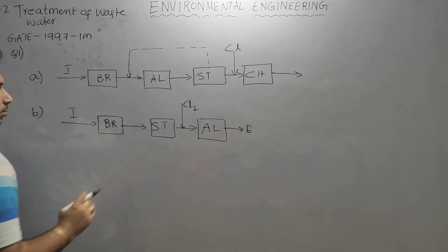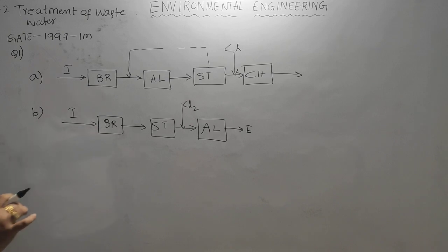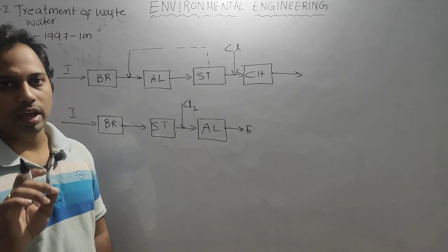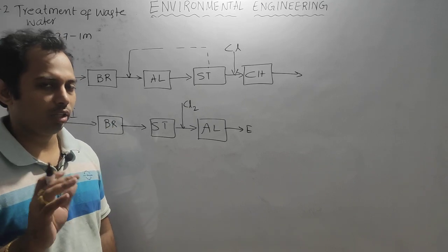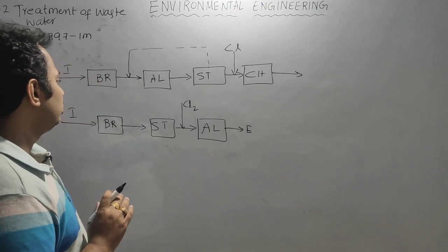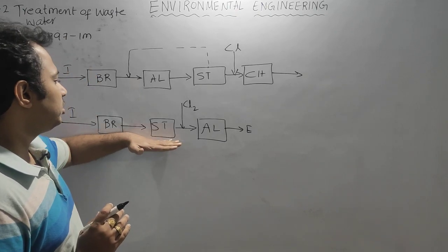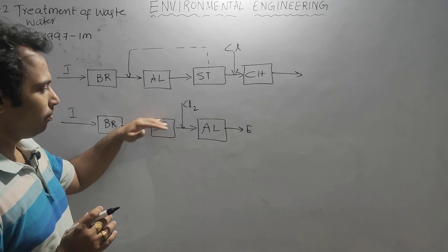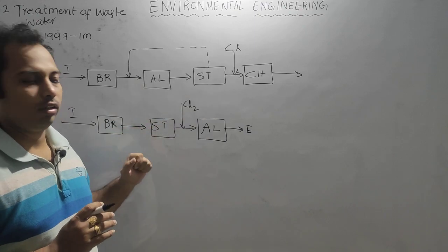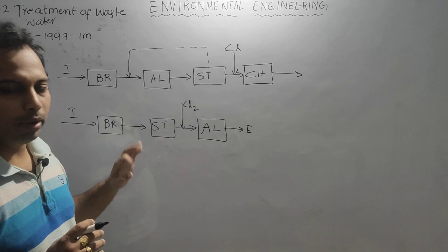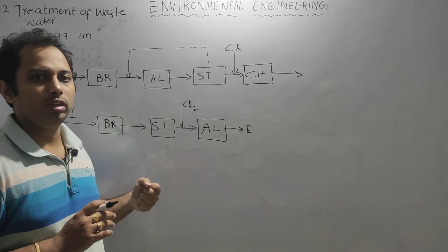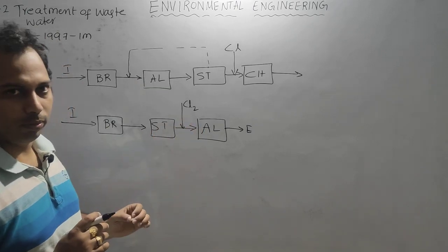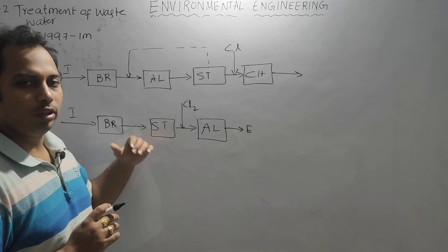See, if you look at this option, generally a proper aerated lagoon does not have any pre-treatment. So this system is not needed. The biological reactor and the sedimentation tank, with sludge going from the sedimentation tank into the aerated lagoon, generally is not needed. But if you want to reduce the BOD before sending it into the aerated lagoon,